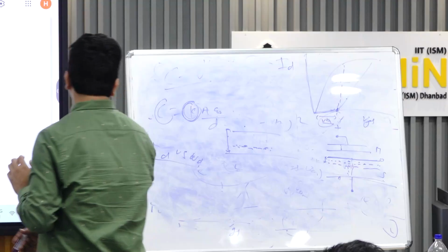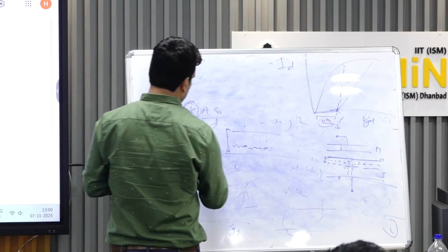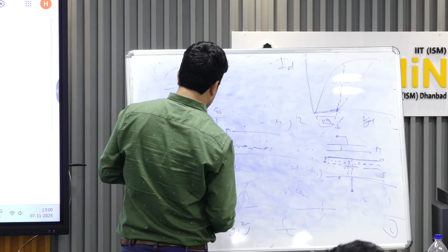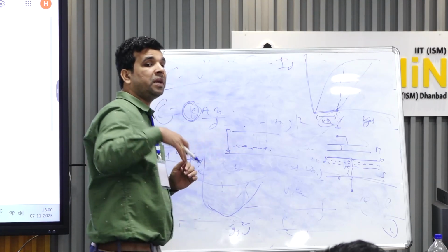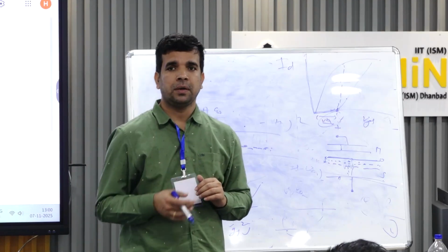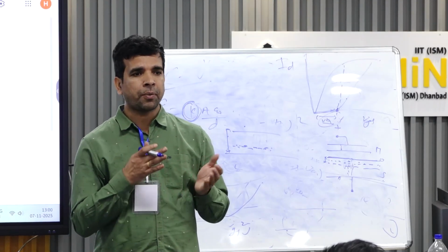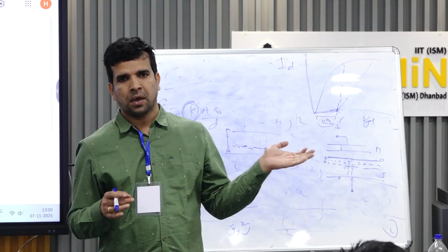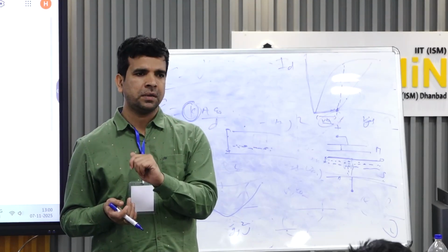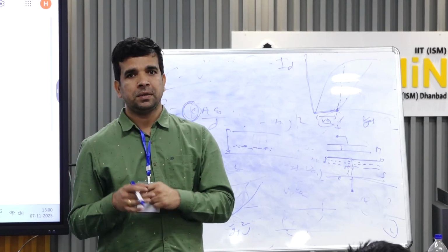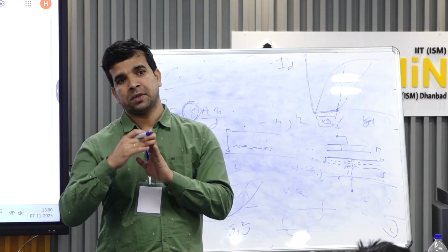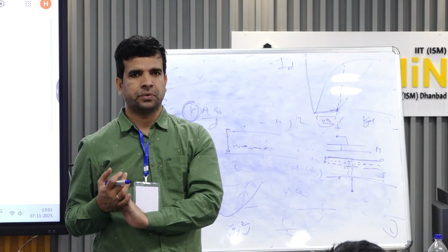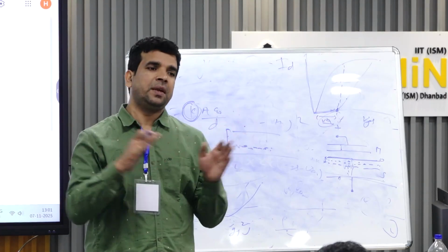So after this threshold voltage, of course, you can increase. Only after this voltage, if you increase, will it give you the characteristic ID versus VG. But if you go very high, then of course it will damage your device. There is soft damage and hard, catastrophic failure. Soft damage, in terms of the trapped charge or other things, can get recovered. But damage can be in the form of bond breakdown also. If you increase the electric field very high, then that will give you catastrophic failure also. So of course, don't increase voltage very high.